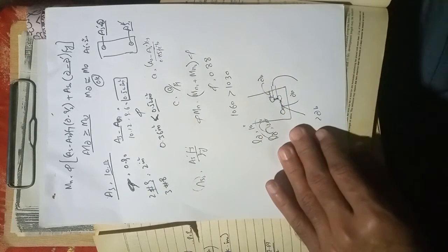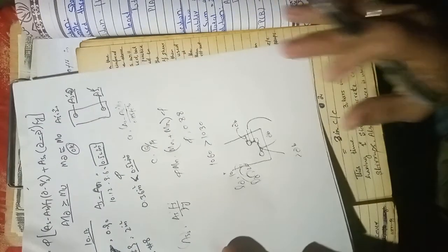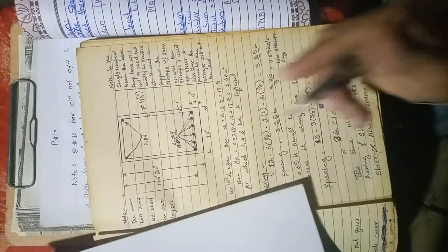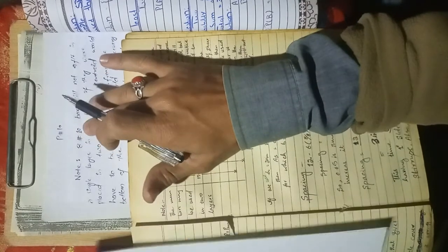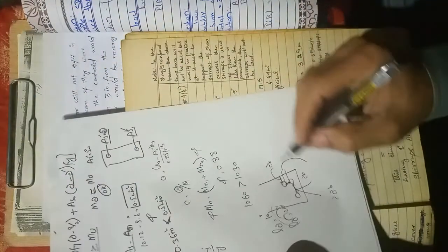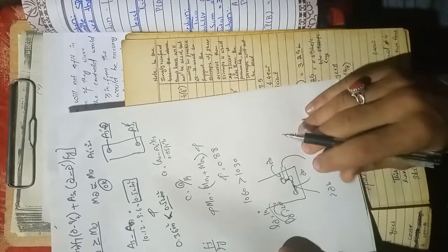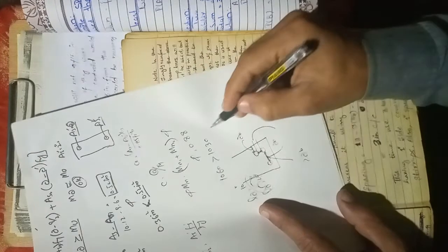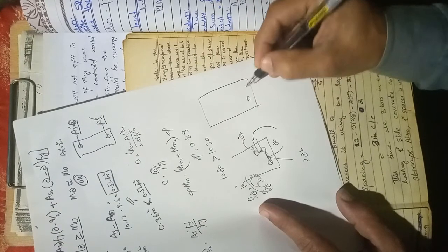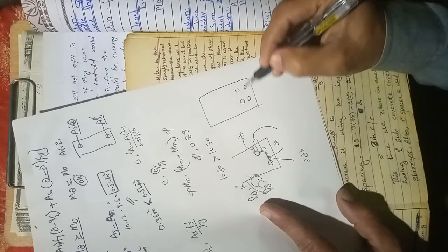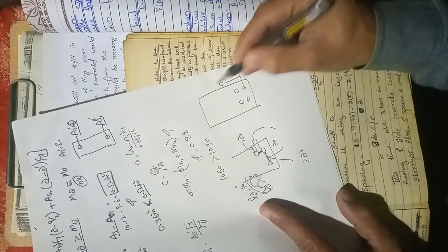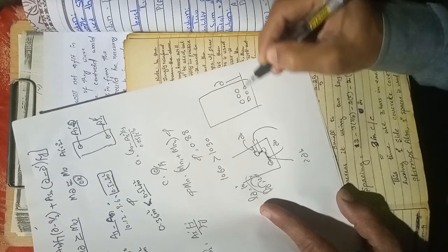That is why we have to place the bars in such an arrangement that it fulfills the ACI detailing criteria. But as here we are choosing 8 number 10 bars, practically it is impossible to place such bars to satisfy the criteria that the spacing should equal the diameter of the bar. So what if you place the bars in two layers? It will produce another problem for you, because we are taking the effective depth assuming that the bars are placed in one layer.